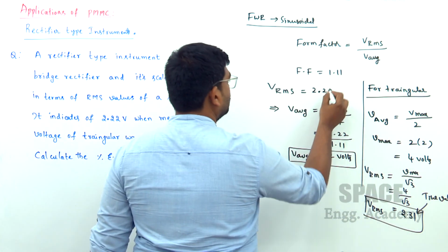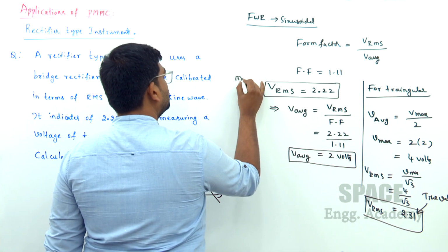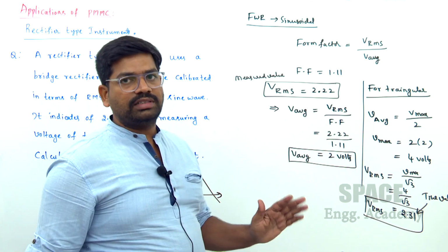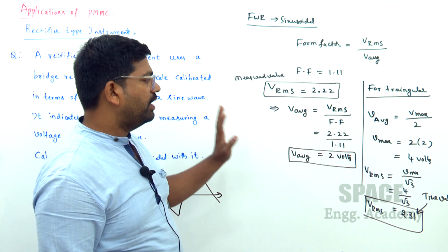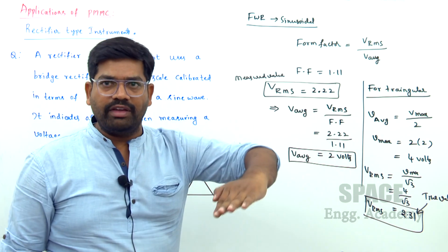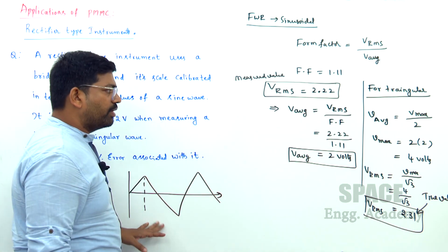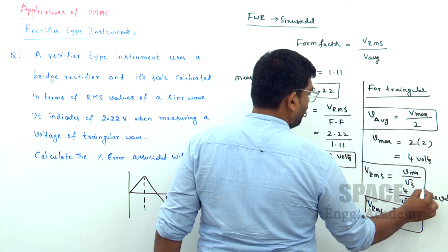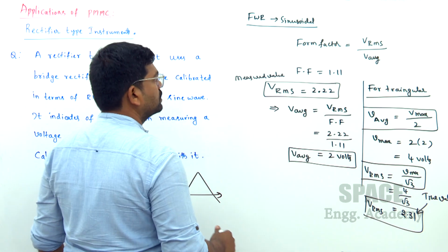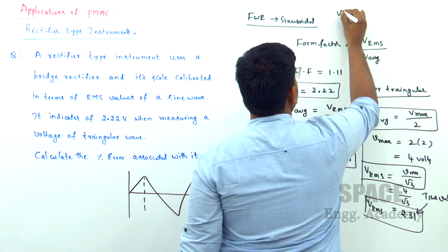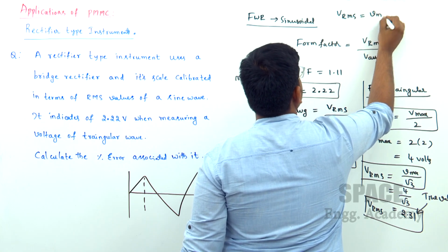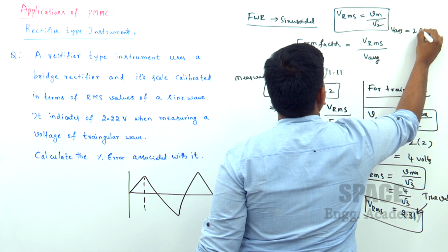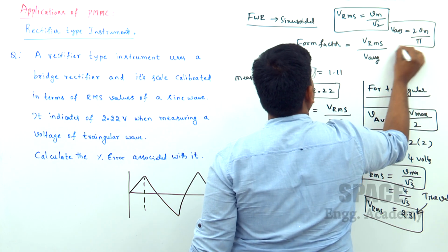But what we are measuring here? This is measured value. So, their difference come automatically. If you give sinusoidal quantity, then absolutely there won't be any error. You are designing for sinusoidal waveform, but you are applying the triangular waveform, right or not? This is the relation for RMS average for triangular. Okay. For sinusoidal, what we get? Vrms will be Vm by root 2. V average we know that 2 Vm by pi, because you are considering full wave rectifier output.